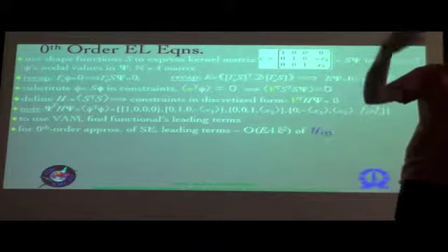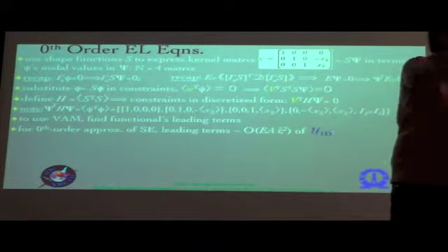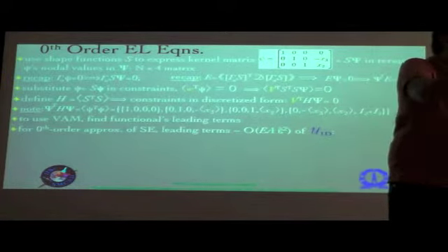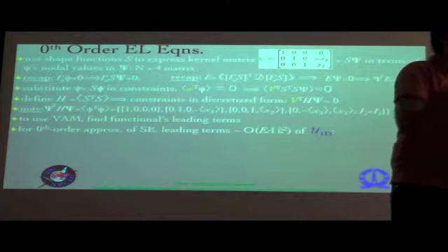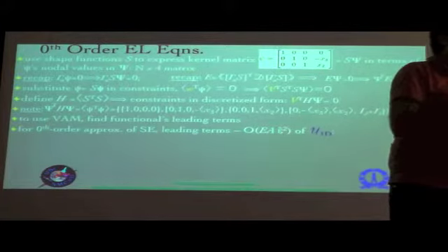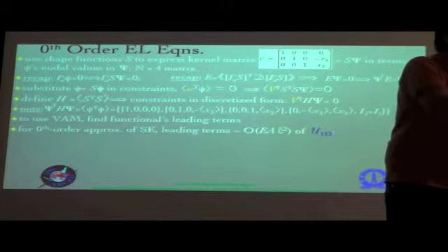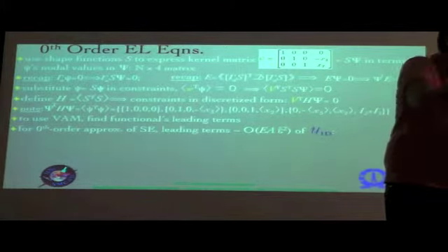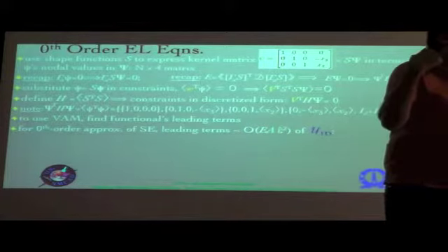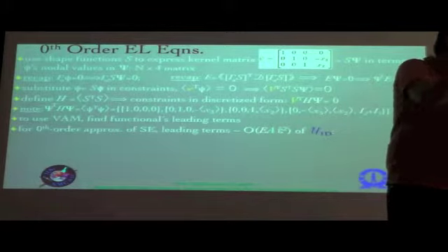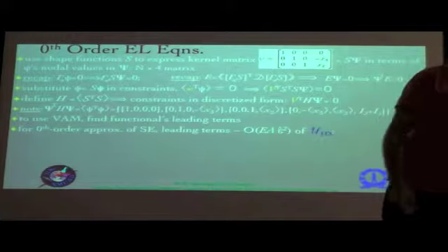On the other hand, the way we introduce the warping constraints is when we are dealing with a cross-sectional problem. We are not even bothered about the length of the beam. It's a specific reference cross-section that we are dealing with. So the root G doesn't come into picture at all. See, basically what you have is x1, x2, x3 are Cartesian coordinates, but x1 alone is a curvilinear coordinate. Your x2 and x3 are still linear coordinates, and that's why you see that anything dealing directly or purely with the cross section does not have that root G. Whereas if that is coming from a volume integral and partly the inner integral is being calculated, then you have that root G term coming into picture as well.